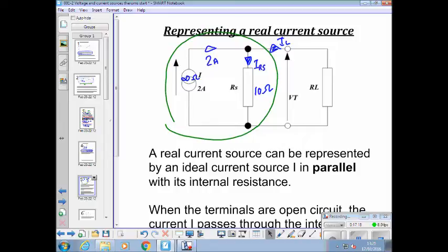Is that why, like on data sheets, they always state them? Yeah. Power sources. I mean, if you buy a regulated power supply, and I expect you've got a lot where you work, you can switch them between constant current and constant voltage, can't you? You familiar with that or not? We've got some here where you either switch to hold the current steady and let the voltage drift up and down, or you switch to hold the voltage steady and let the current drift up and down. So you can choose. But you can't have both. It's not possible. And that holding is only within a certain range. Once you go beyond the specification, then the voltage or current will start to drop anyway.